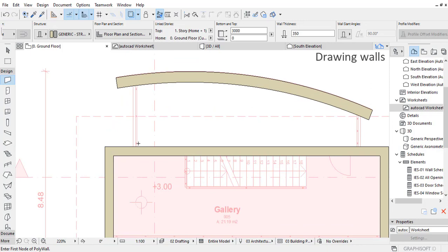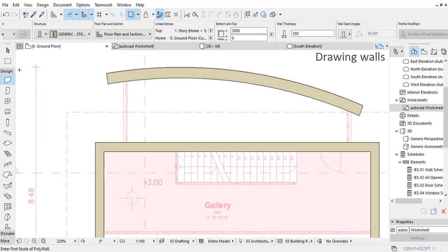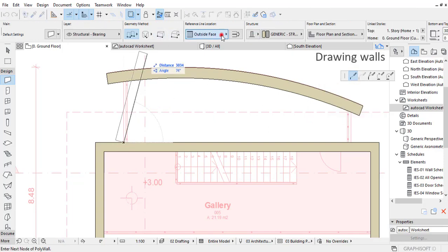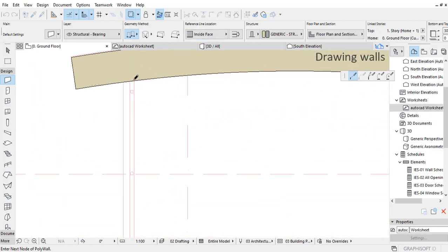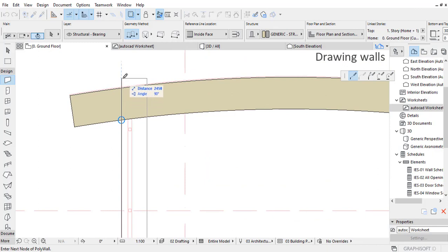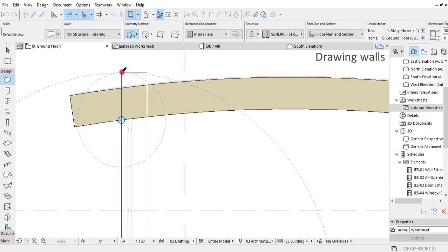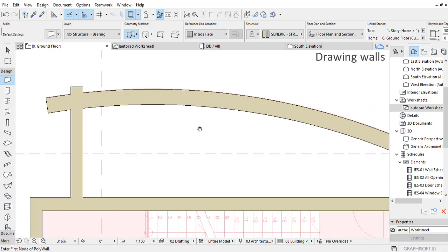And there are going to be walls here as well, so we'll draw some walls here as well. Make it 300 again. Start drawing from here, change the direction to inside, and I don't want to draw it up to here because I'll get a gap, so I'll draw past this wall actually, and then trim away that portion.